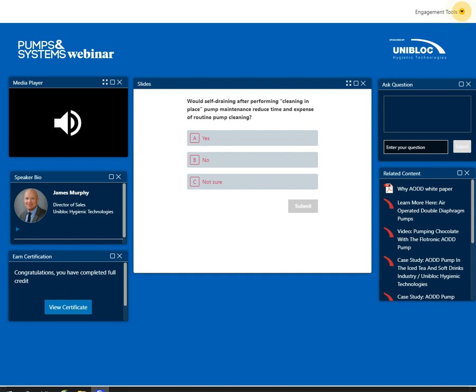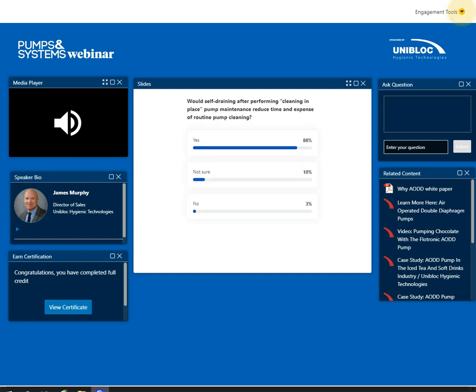I'm going to go ahead and move us over to the answer. Yes. Okay. Good deal. So I think we can all agree if we don't have to take pumps and pipe work apart for cleaning, that's obviously just going to eliminate a lot of maintenance and overhead as well. So I would like for you to be cognizant that traditionally diaphragm pumps were not used in a CIP application just because of the fact that they couldn't handle the pressure, and sometimes they couldn't handle some of the temperatures and things of that nature.